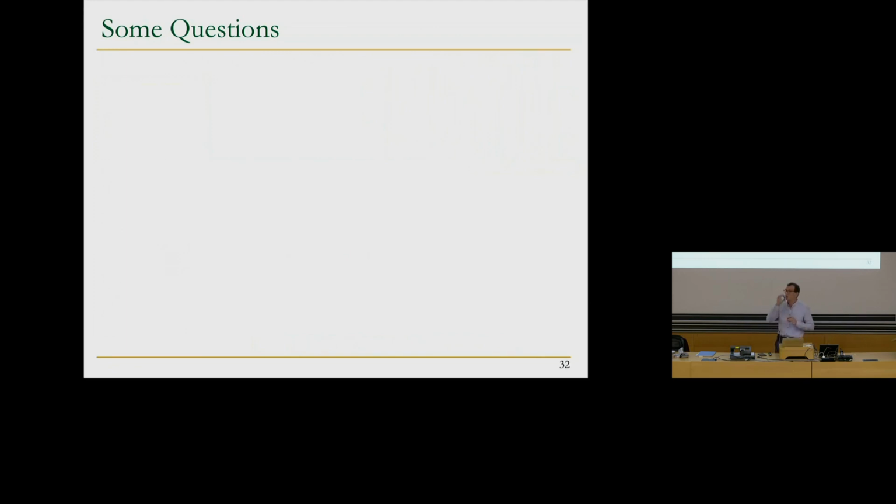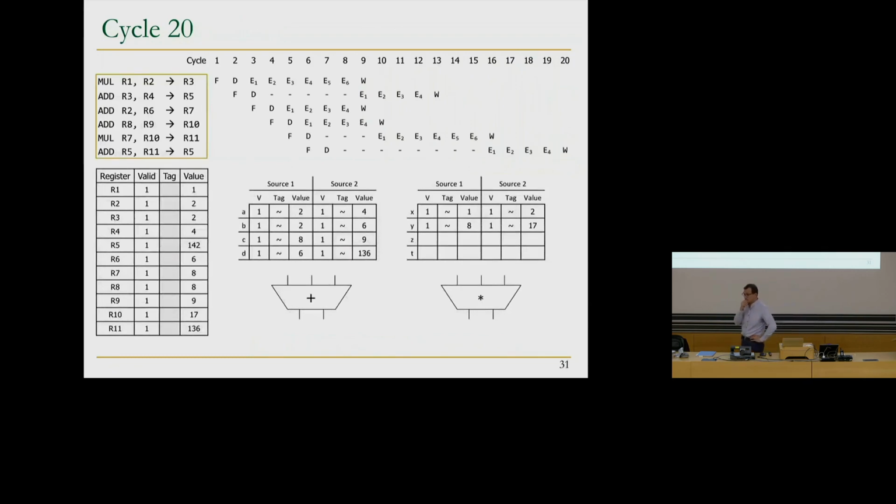If one of those reservation stations of a functional unit is full, does it stall with dispatching? Yes, exactly. So basically, if you cannot dispatch, if there's no available reservation station, that's step 1, if you remember. Does it stall the dispatching for just those instructions or for all instructions? So it stalls dispatching because you need to allocate a reservation station entry in order, because everything else is dependent on it in terms of renaming. But instructions for other instruction units can be dispatched.